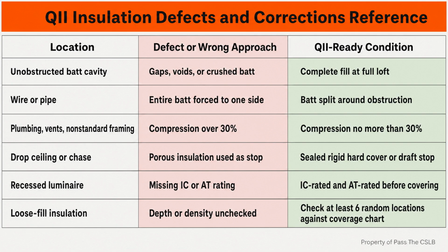Consider a hypothetical project where the board delivery is early and the drywall crew has an opening in its schedule. The fastest looking decision is to let the crew close one floor while the rater is still booked for the following day. That decision trades a small schedule gain for concealed conditions the rater was supposed to see. If the work cannot be verified as prescribed, reopening walls becomes possible. The disciplined decision is to protect the hold point even when another trade is standing ready.